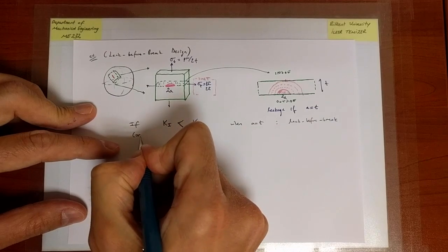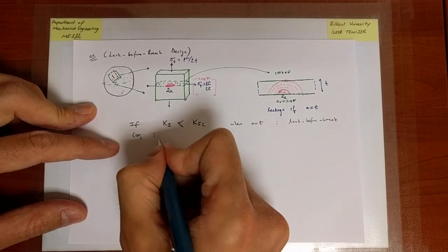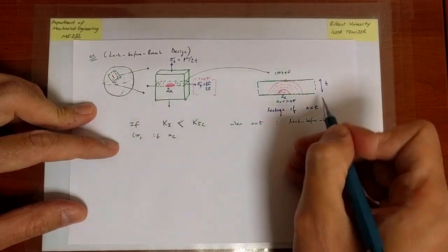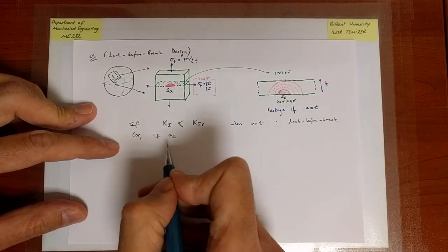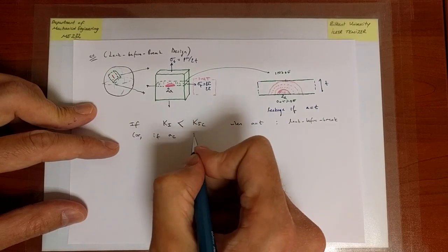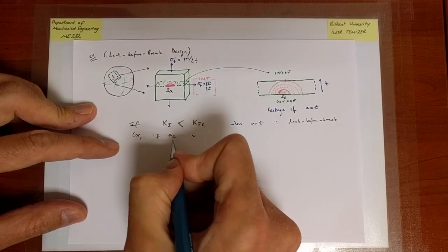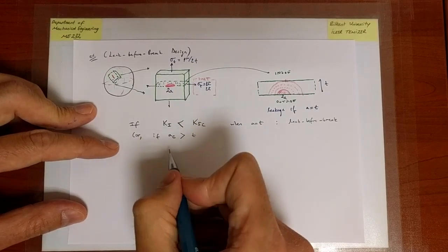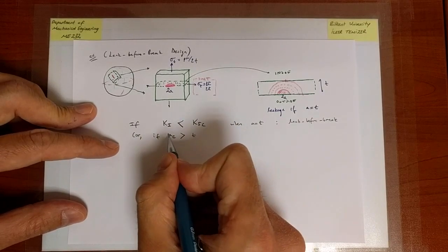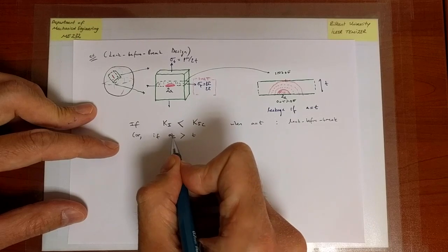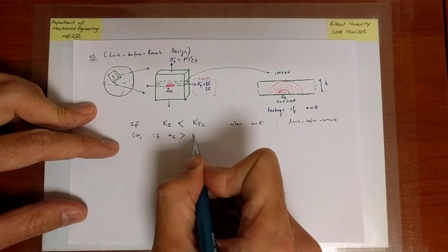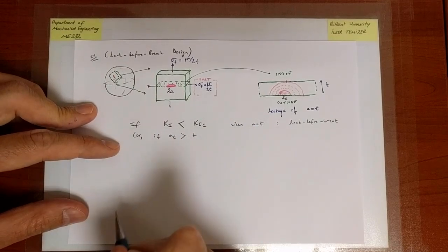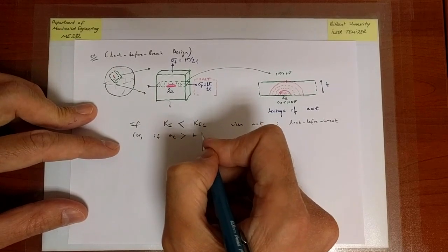Another way to check this would be that you calculate the critical crack size for fracture for your loading scenario, and you compare it against the value of the thickness. If the critical crack size is larger than the thickness, the crack needs to grow to a value of a_c for fracture to happen, but before it reaches a_c, it will hit the value of t and the pressure vessel will leak and you are safe from fracture, right?